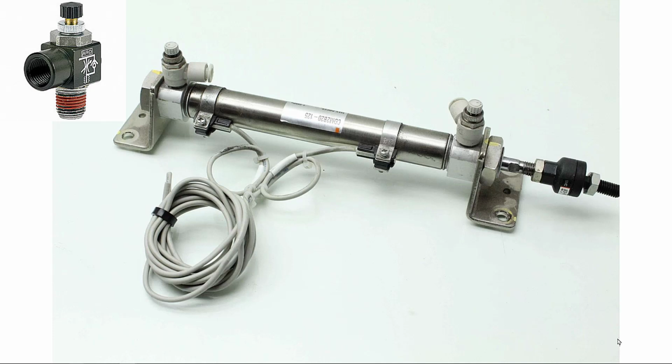When air is coming in this fitting, and by the way, our nice fitting there is threaded for a national pipe thread. The one on the cylinder is a press-in tubing with a release. I'm sure you recognize this stuff. So when pressure is applied to the device on the cap end, it opens the check valve and goes into the cylinder freely. So just remember that you are always adjusting the flow control on the exhaust side.